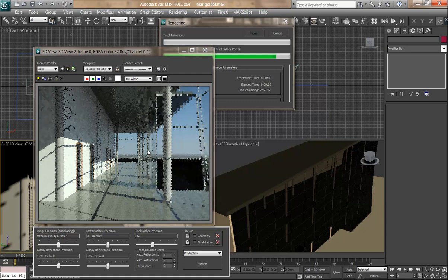You put the geometry in and select all materials in V-Ray. Revit's going to give materials no matter what. Everything's got a material, whether you like it or not. But that's a good thing because you do a wall or a floor in Revit, and it's got a material called concrete or something. Then in Max, you don't need to go and find all the things that need to be concrete. You just find that concrete material and replace it with a V-Ray material, and that changes anything that's concrete into the new material.